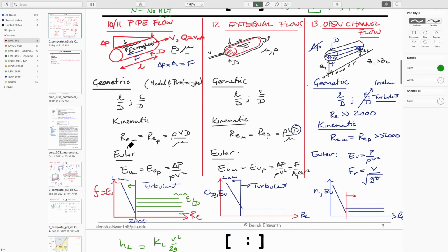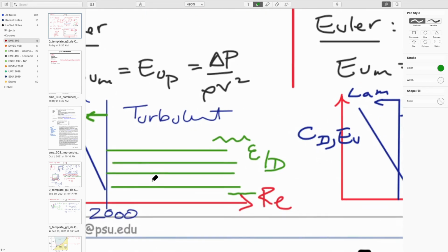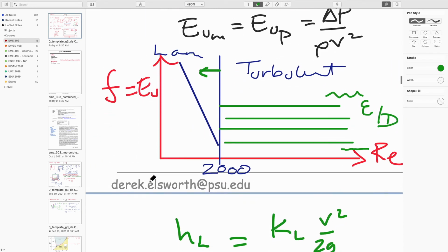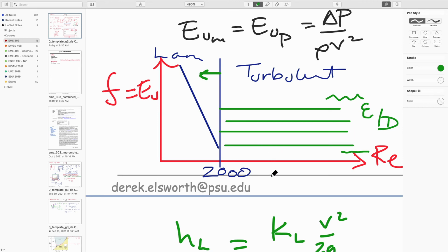And we'd find that the flow is a function of the Reynolds number and the Euler number. And we could place it on a chart, which I can make bigger, which would look like this. So if we plot, for instance, the density and the velocity and the diameter of the pipe relative to viscosity, which is Reynolds number, on this axis, and if we plotted the Euler number, which is the pressure drop along the pipe relative to the density of the fluid flowing and the velocity squared, and we did a whole bunch of experiments with a pipe using different velocities. And of course you see that velocity turns up here and it turns up here as well, so it's kind of an interesting layout.